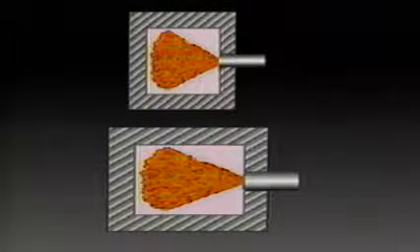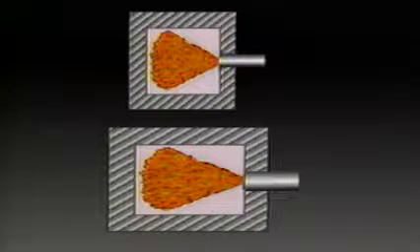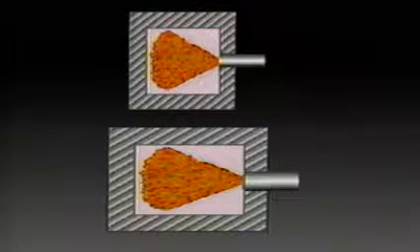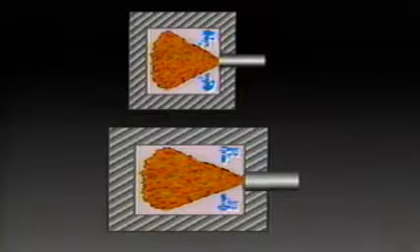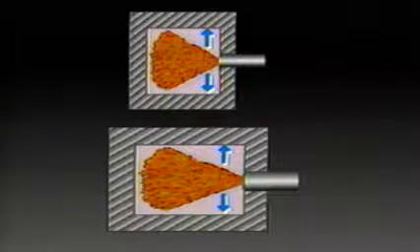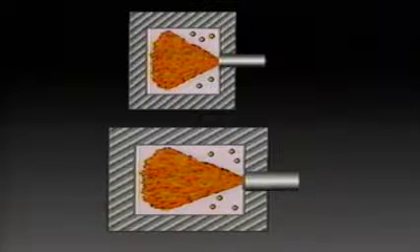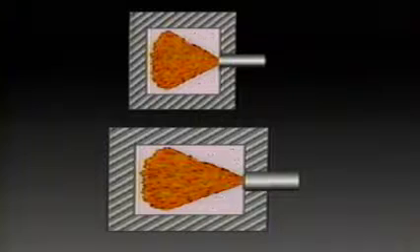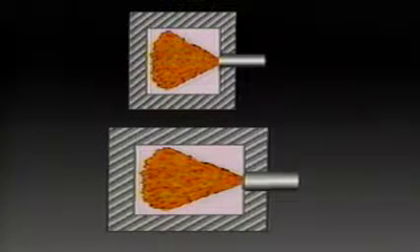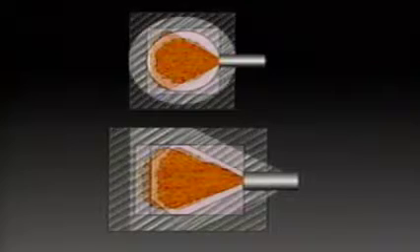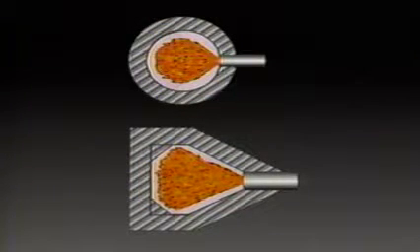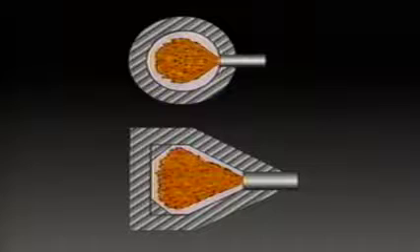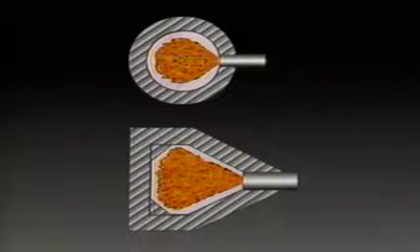Combustion chambers can come in many sizes and shapes. When an old-style combustion chamber has a profile like these two, and old-style non-flame retention burners are used, there will be some cooler corners and surfaces that the flame does not fill. The result is less rapid evaporation and incomplete combustion of the droplets. Modern flame retention burners are less affected by variances in chamber configuration. The secret of high fuel efficiency is complete and rapid burning of the fuel oil, so the chamber ideally follows the shape of the burner flame and reflects heat back into the flame.